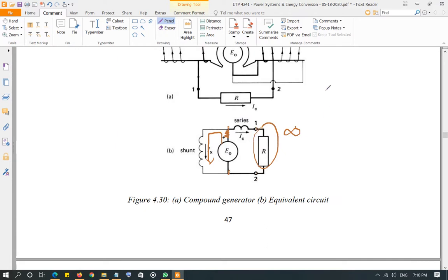Now the disadvantage again, remember, for the shunt generator is when you connect the load, current starts flowing, and first drop is across the armature resistance, which drops the voltage across the shunt field, which draws less current in the shunt field, which will produce less flux, and then induced voltage itself goes down. So what's going to happen over here when the current starts flowing?